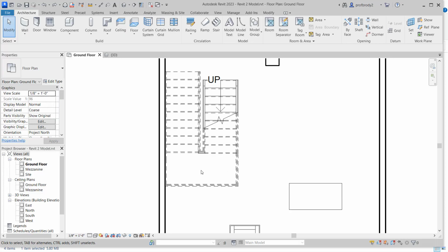Now, if you do have straight stairs, sometimes you have to do something like draw a wall under the stair to prevent people from walking underneath. That's another rule, another code rule. You're not allowed to walk under those awkward spaces. To do that, I'm going to draw two short walls under the edge of the stair. And I'll just do that real quickly.